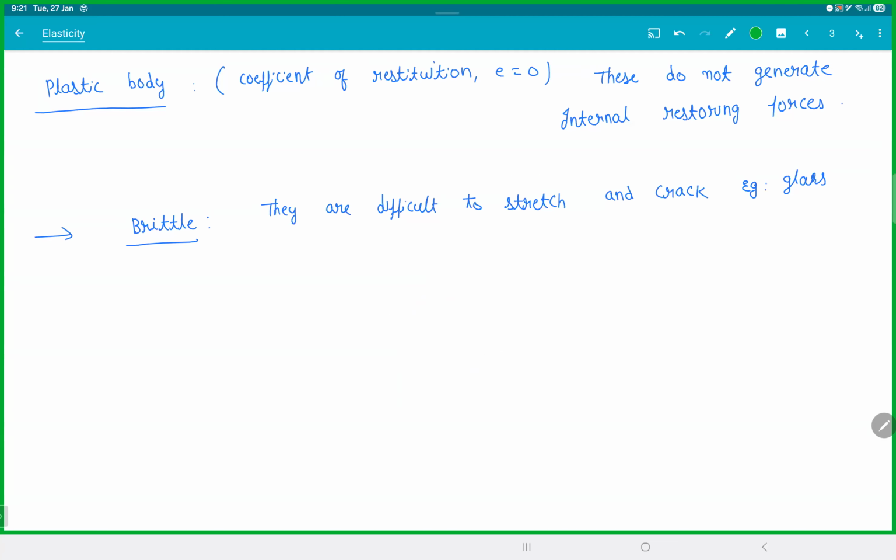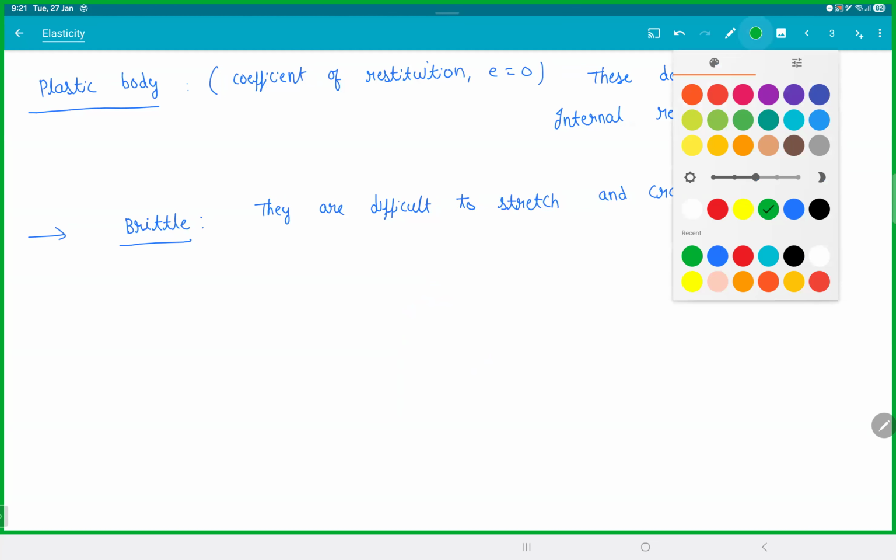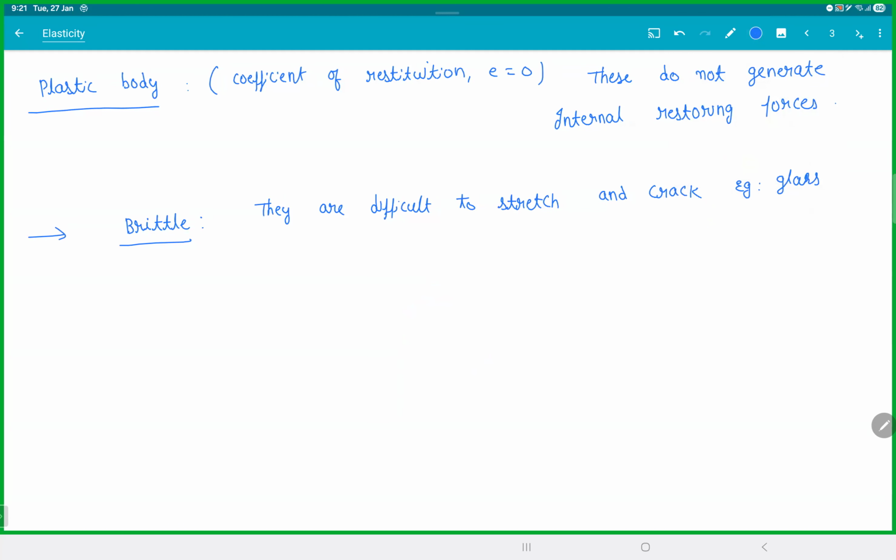Now in India it may not happen, but when you go to cold countries, they have this problem: the entire glass of the car becomes ice. So what some people do is boil some hot water and put it on the glass to melt that ice. The most nonsense thing you can do. The moment the hot water touches that glass, that part will start expanding because it is getting heated up, while the surrounding is contracting. The glass will develop stress and the whole glass will break.